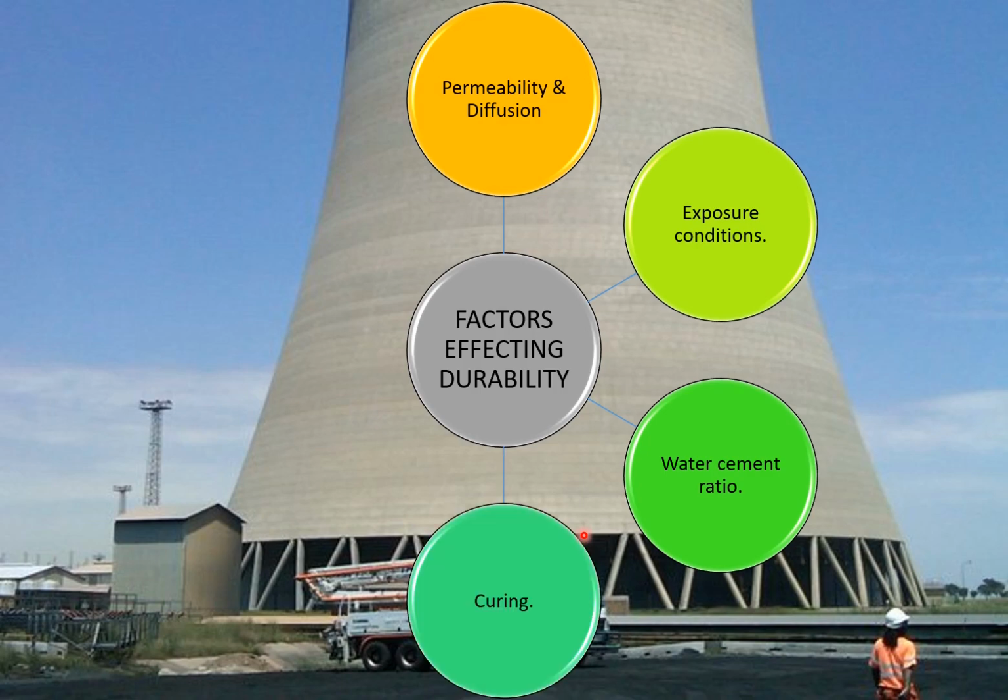Then the other significant property is the effectiveness of the curing. The curing has to start on time, as early as possible once the concrete has attained its shape in the formwork. The curing has to be effective, because if it is not, cracks will develop, and those cracks will guide the movement of water, chemicals and acids through the concrete.